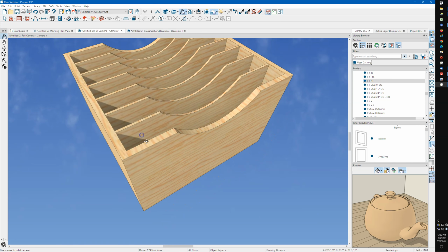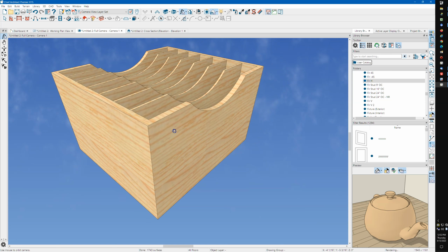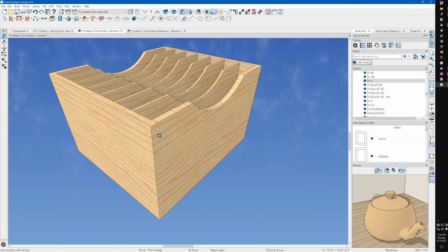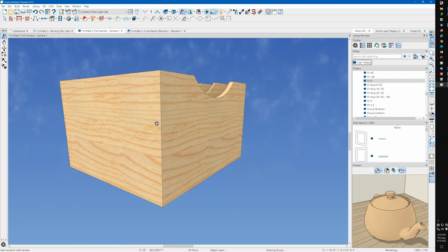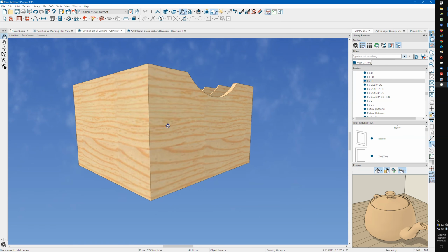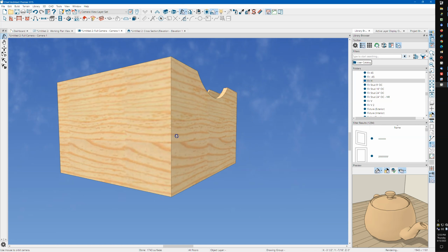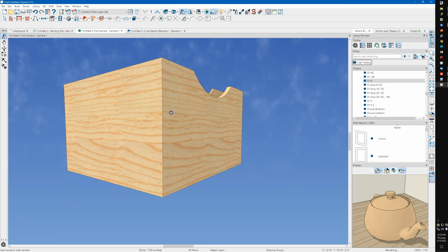Now, one of the problems I always have with wood grain like this is that it's not very accurate, I guess, because the way the program works, the origin of all this wood grain is the same, so it wraps around. It doesn't look different enough.